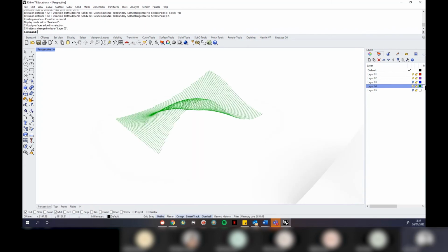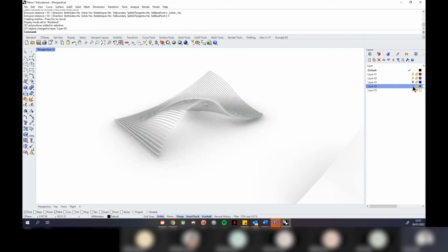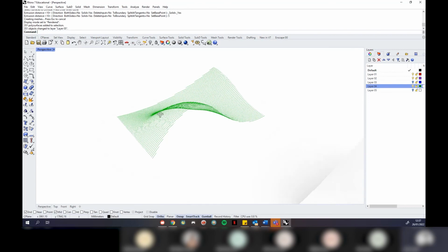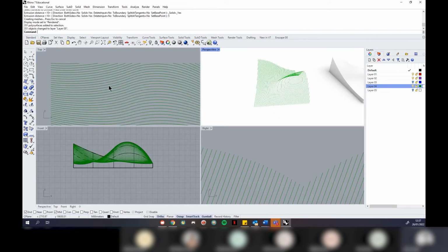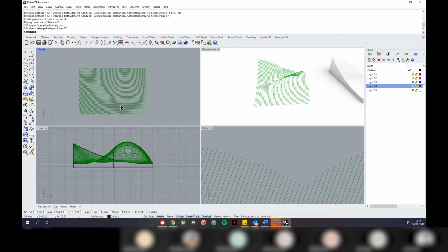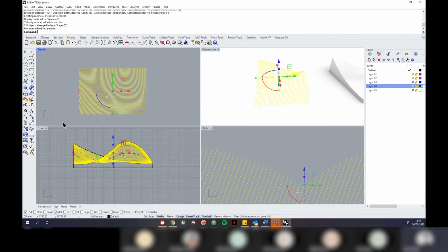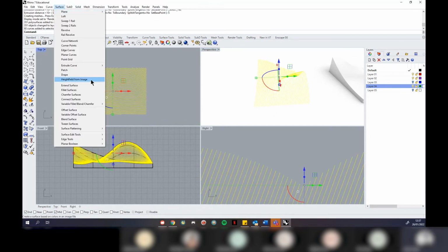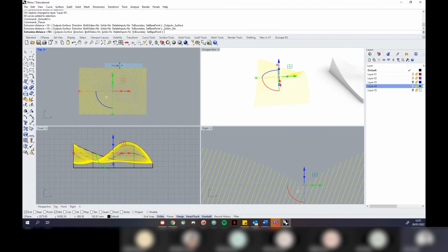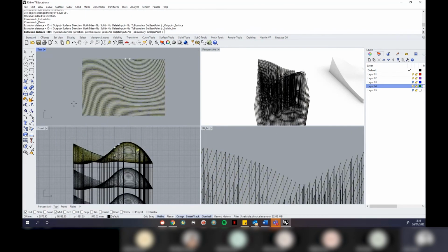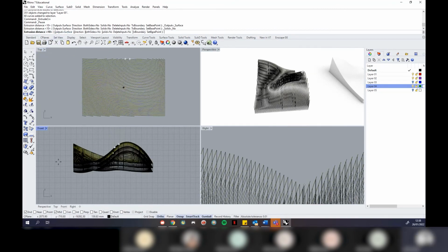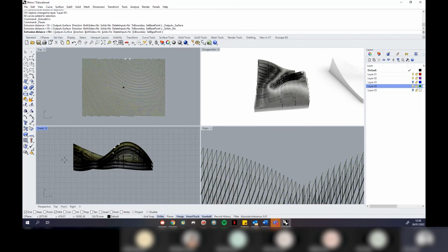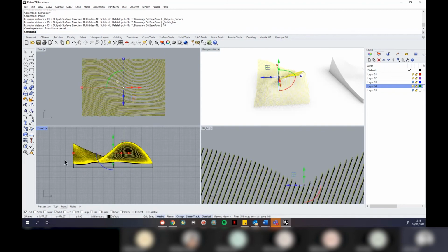Bring back the curves in the opposite direction this time. Hang on. Yep, that way. And I would just do the same thing again, essentially. So I'm going to select all of these. I'm going to go a bit faster through it this time. So I'm going to go surface. I'm going to choose where to offset. So I'm going to choose a height. My height value, I think, was 10 before, so I'm going to do the same thing again.